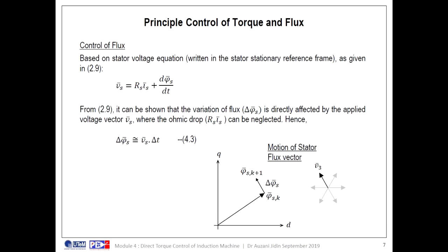Now we will discuss the principle of control of torque and flux. Based on the equation shown in the slide, the variation of stator flux depends on the stator voltage vector, and the ohmic drop is very small in practical situations, so it can be neglected.